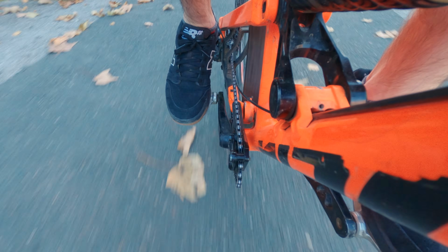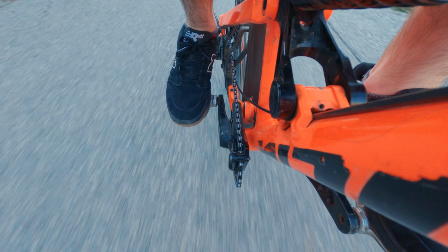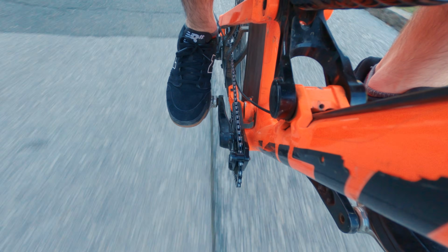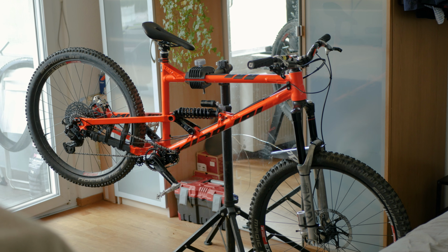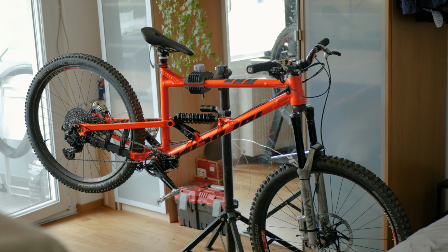The lack of stiffness only really becomes obvious when sprinting in the smallest cog. It's not a major issue, but you can feel a slight vagueness through the pedals when putting down full power. It's safe to say that an idler mounted in front of the chainring is best attached directly to the main frame if possible. The ISCG tabs were probably never intended to handle forces of this magnitude.